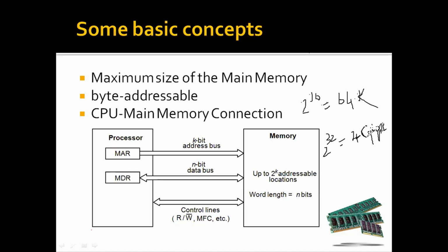When a 32-bit address is sent from the processor to the memory unit, the higher order 30 bits determine which word will be accessed. If a byte quantity is specified, the low order 2 bits of the address specify which byte location is involved. In a read operation, other bytes may be fetched from the memory, but they are ignored by the processor. If the byte operation is a write, however, the control circuitry of the memory must ensure that the contents of other bytes of the same word are not changed.